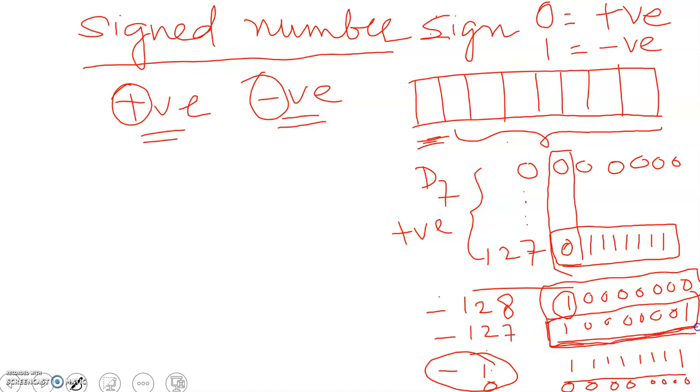So this is how a negative number is stored in the microcontroller. We will see some operations to understand how signed numbers are added and subtracted, and how the overflow flag is affected. Our intention is to understand how the overflow flag is affected.